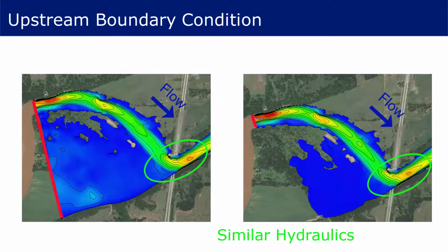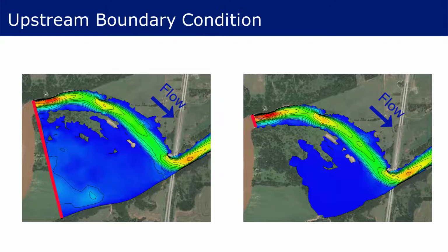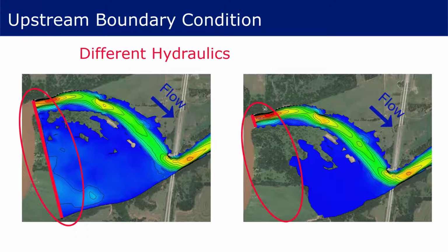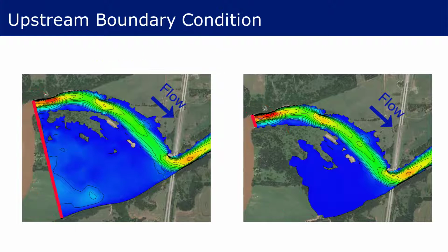Both configurations produce hydraulics at the bridge opening that are essentially the same, suggesting that either boundary condition is acceptable for hydraulic analysis. However, for sediment analysis, the difference in inlet conditions may produce different transport behavior, including differing calculated capacity supply loads.